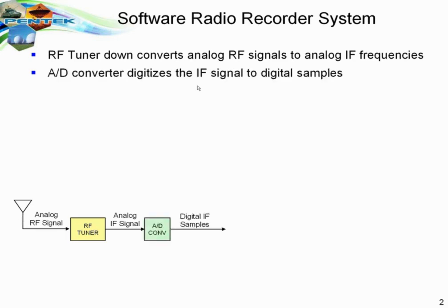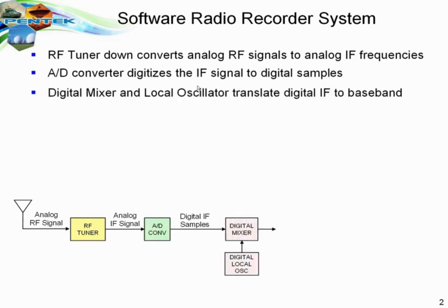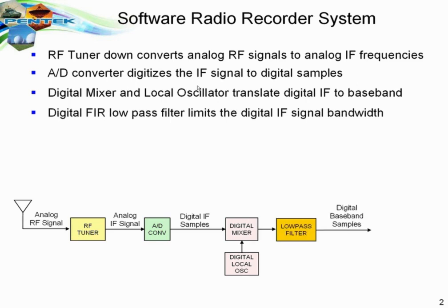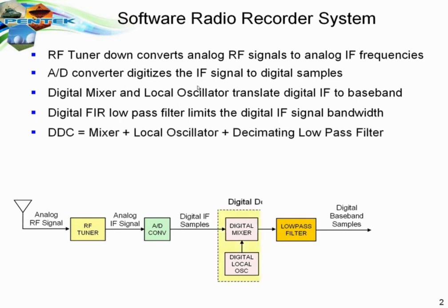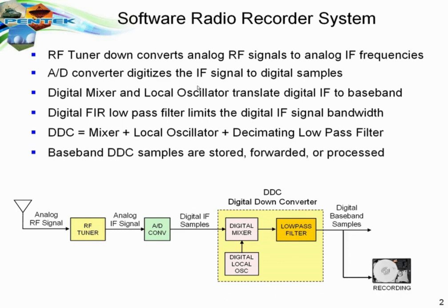We have to synchronize the capture across multiple channels so that in the case of a phased array antenna, each antenna element is being digitized synchronously with the others. We have to eliminate bottlenecks in terms of data flow to the disk drives, to the storage, through the RAID controllers, which are the interface to the hard drives. We also have to eliminate overhead that's typically associated with operating systems.